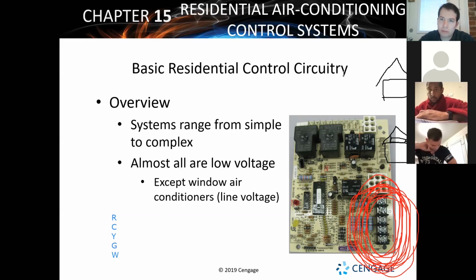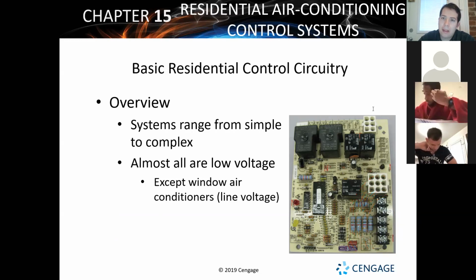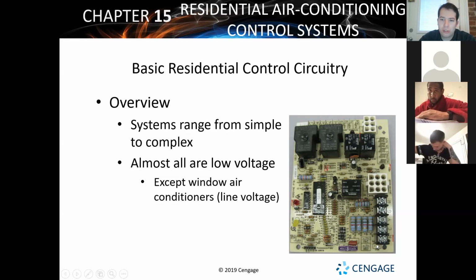So, you've got it where the control board and everything like that. The typical thing with these is you're going to see a basic layout. You're going to have one section that'll be 24 volt controls as far as connections to your actual thermostat wiring. And that's what we're seeing with this one right here with these screw terminals. Your other connections you're going to see are typically high voltage connections.